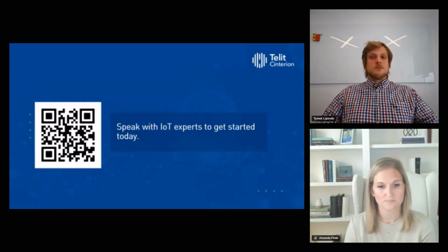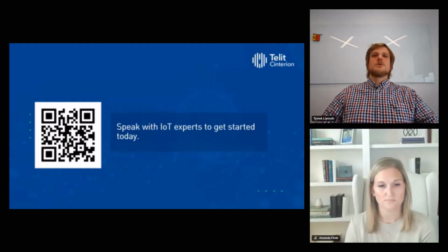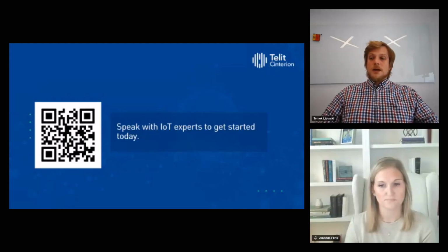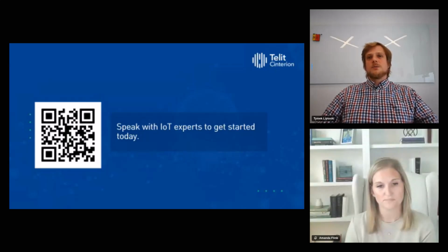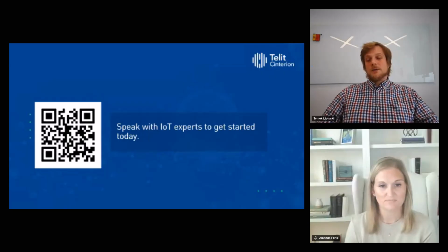The device can recover if it's moved from one location to another and it forces the modem to use a different base station, but this will have some current consumption overhead because the network is not aware of it. So it will break the connection and we have to establish everything from scratch. Of course, NB-IoT is slower, and the key benefit from using CAT-M is that usually we want to download more than we want to upload. CAT-M works the other way around. It has higher bandwidth on the uplink than the downlink. So we really need to validate what we need for our application.